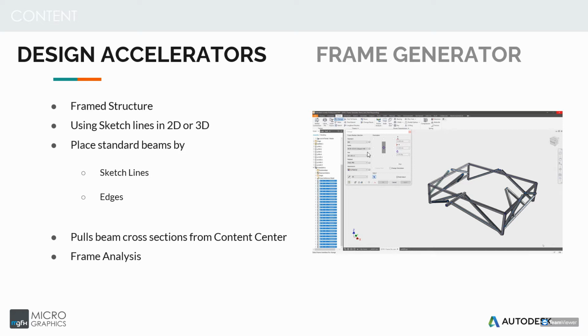Okay, another interesting thing is once you place these beams all together, you will open up all the grayed out tools here where my mouse is highlighted, and that will allow you to have some end treatment. So in the corners where they meet, you can either have them mitered or maybe put in some end caps depending on what you need. Okay.